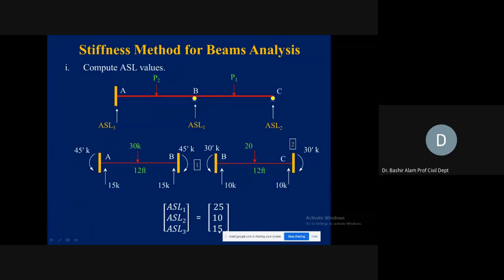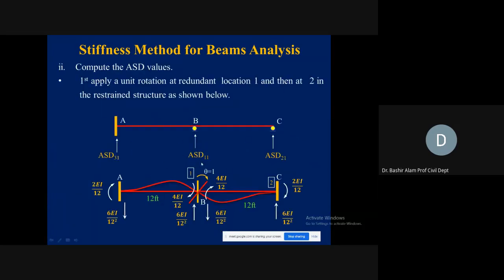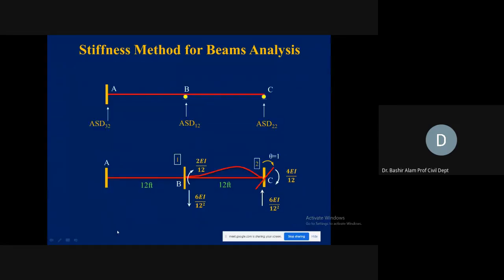अब ASD मैट्रिक्स कहाँ से बनाएंगे? यहाँ से बनाएंगे। Already ये था हमारे because of the unit displacement application corresponding to D1। तो अब यहाँ पे आप देख लें ASD1 क्या होगा। ये दो जो आपके यहाँ पे रिएक्शंस आ रहे हैं इसका algebraic sum लेंगे। तो how much is this now? This is coming 0 now, plus and minus, so the same magnitude, this is becoming 0। ये क्या होगा आपका? ASD21 कितना होगा? 6EI और L स्क्वायर, और ASD31 क्या होगा? 6EI। So first column of the ASD matrix will be generated।